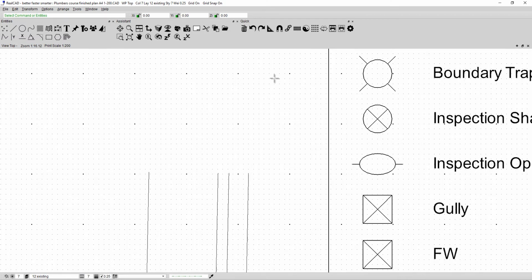The first thing I'll do, this is before, I'm not going to draw any correct line at this point. I'm drawing a black line, so I'm going to come down here to the very bottom of my screen. If you look down the bottom, there's a clone command. I'm going to click on the clone command, and then pick a line that I wish to clone from. Now notice that as my cursor comes over the top of the line, a little diamond appears at my cursor, and this indicates I am able to select the item underneath it.